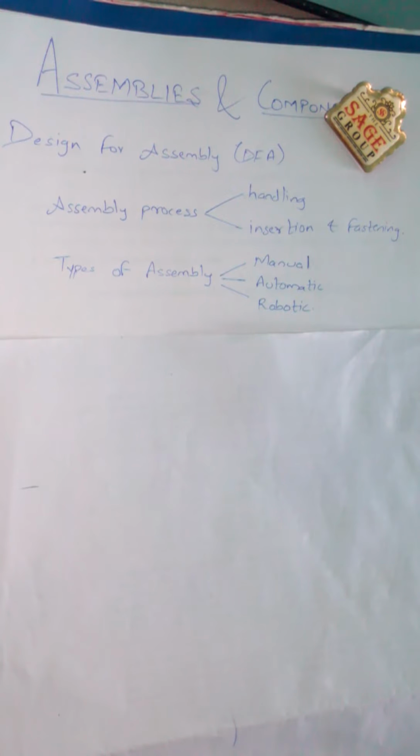Parts that do not require end-to-end orientation prior to insertion, as a screw does, should be used if possible. Parts with complete rotational symmetry around the axis of insertion, for example a washer, are the best.